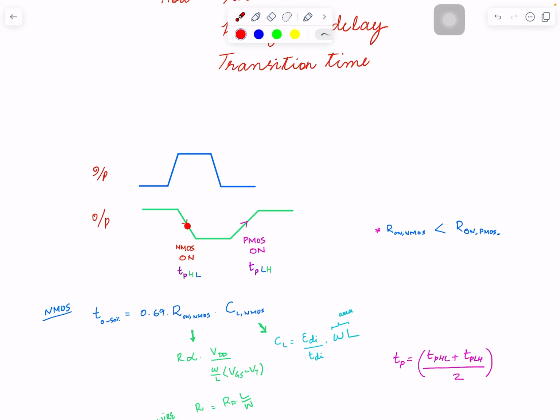You don't need an equation. In physical design, that delay will come through the standard cell library, and I will talk about that. So we will not be calculating this delay manually with an equation. But equations, as I told you, are really helpful for you to understand dependencies.